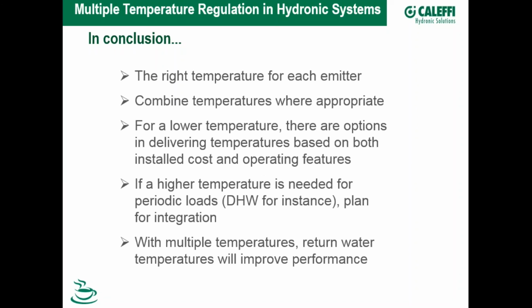Really, from a water temperature standpoint, the first thing I would start with is, what's the lowest water temperature I could run that boiler and still maintain temperature in the building? For instance, when I moved into my house it had an atmospheric gas-fired cast iron boiler.